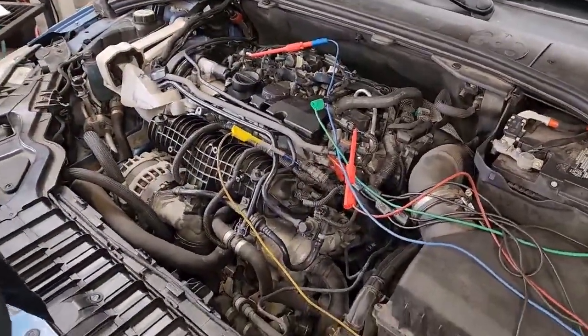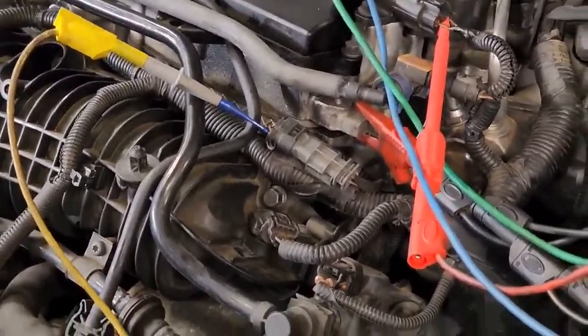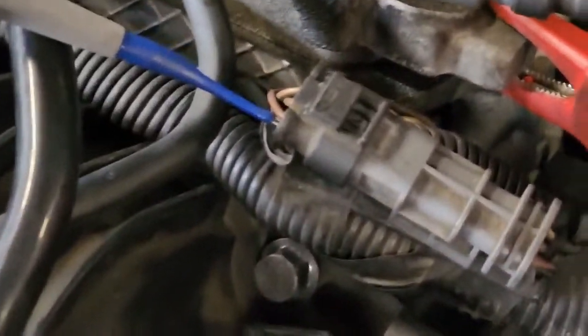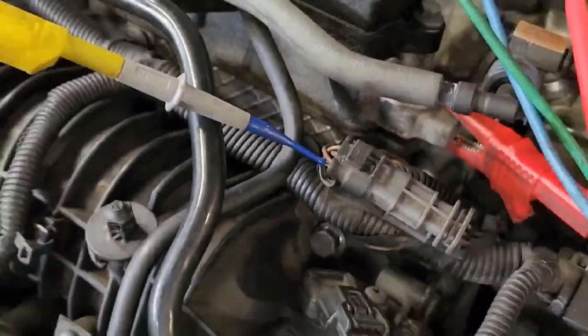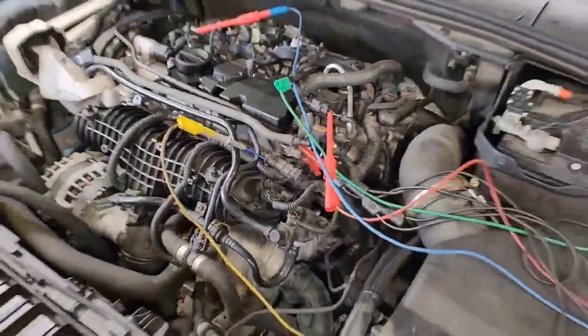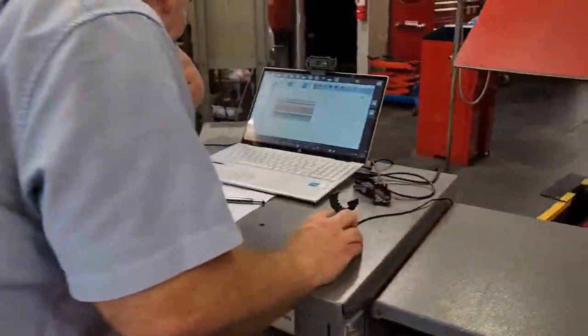This red line is from 3 volts to 1.7. And this blue line is 1.8 to negative 1.5. We're just looking for 0, 5, and then a square wave signal, right? But we're getting these numbers that were all over. That's just because it was on a funky ground. It was on an improper ground.